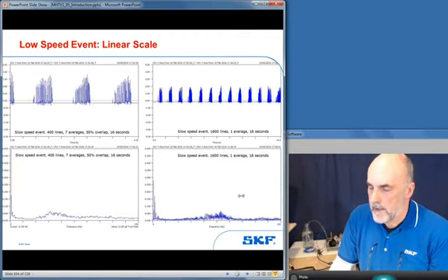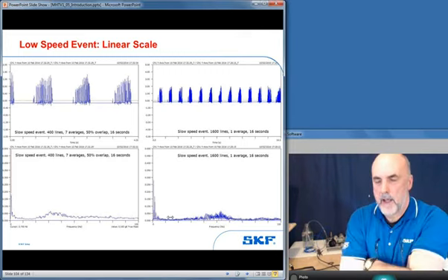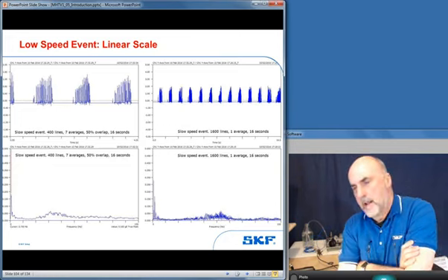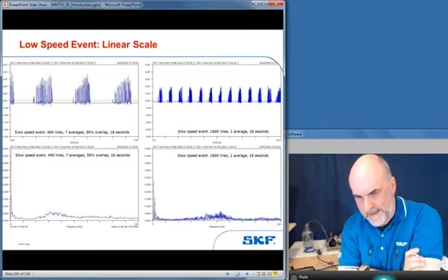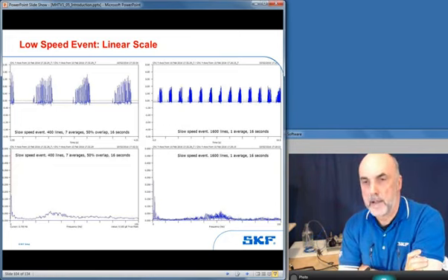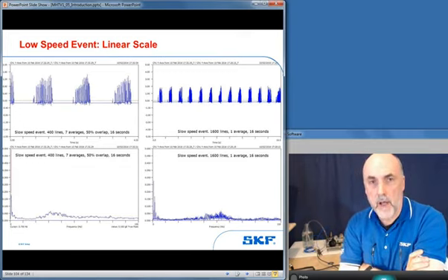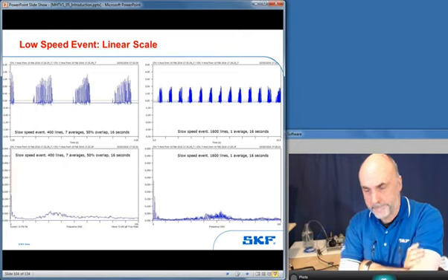There's lots of information and techniques that SKF uses, which relies on the harmonic content of the signal. There's even a patented method called a harmonic activity indicator. The presence of harmonics and sidebands in your measurement is really good evidence that you have got bearing damage.